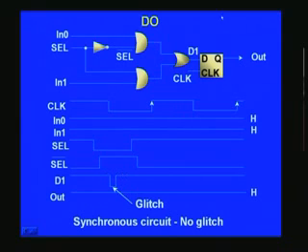And the way to do it is to put the flip-flop here. If there's a flip-flop here, naturally you can rest assured that there are other flip-flops from which other signals are coming. It may even be asynchronous, in which case you cannot directly put it here. You need another flip-flop and then only process other asynchronous inputs, which we will see in the later slides. And here, all this glitch will happen before the rising edge of the pulse. You should keep in mind the total delay of this, and then only select your frequency. Frequency of operation is governed mainly by the total delay that you encounter in a combinational circuit.